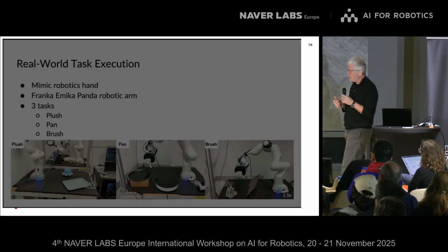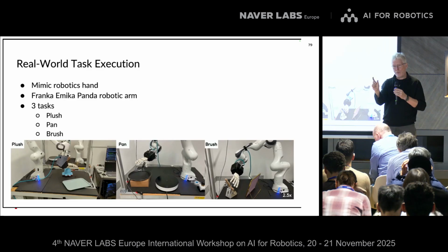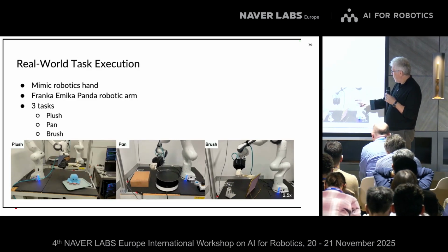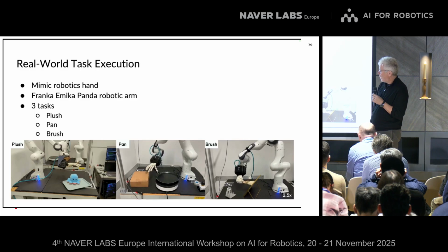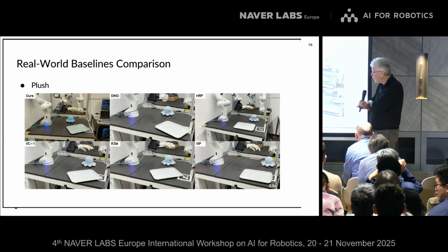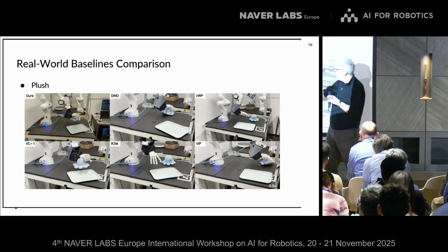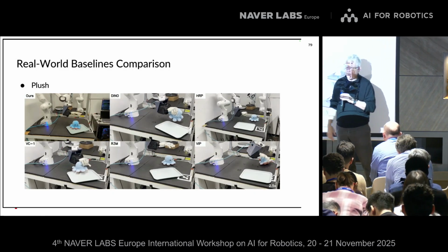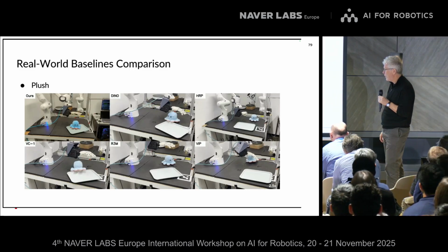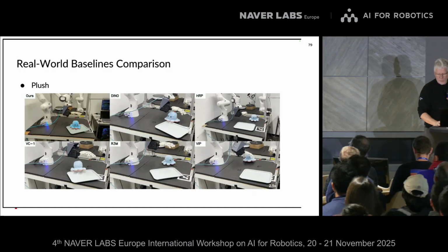This is with the goal of using not just a simple gripper, but a fully articulated hand, built by one of my colleagues at ETH, Robert Katzschmann, that we work with, here carrying out some of those tasks. We've essentially fine-tuned DINO to do a better job at predicting these grasp points, and that improves the results significantly.